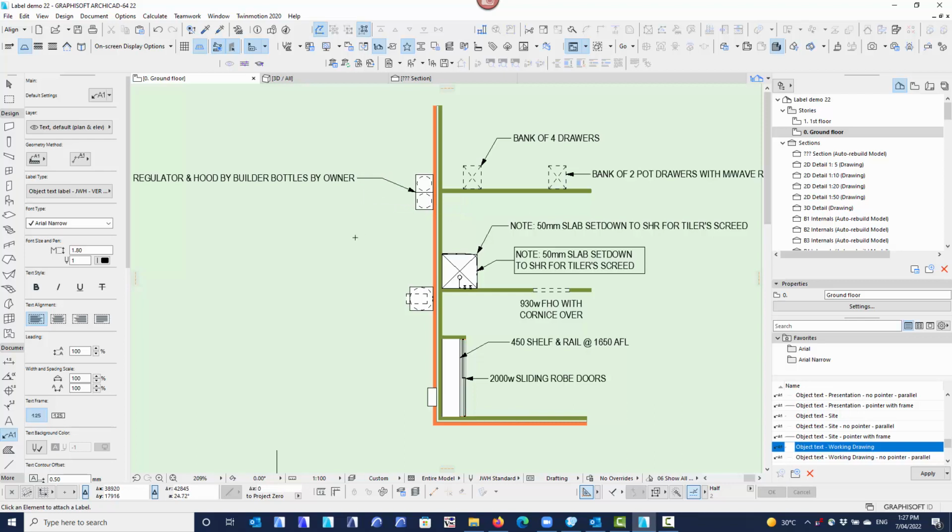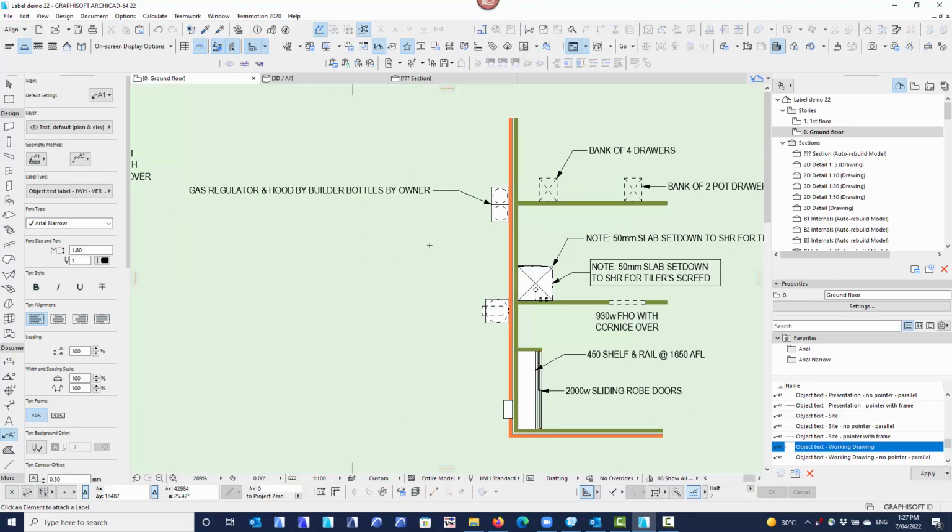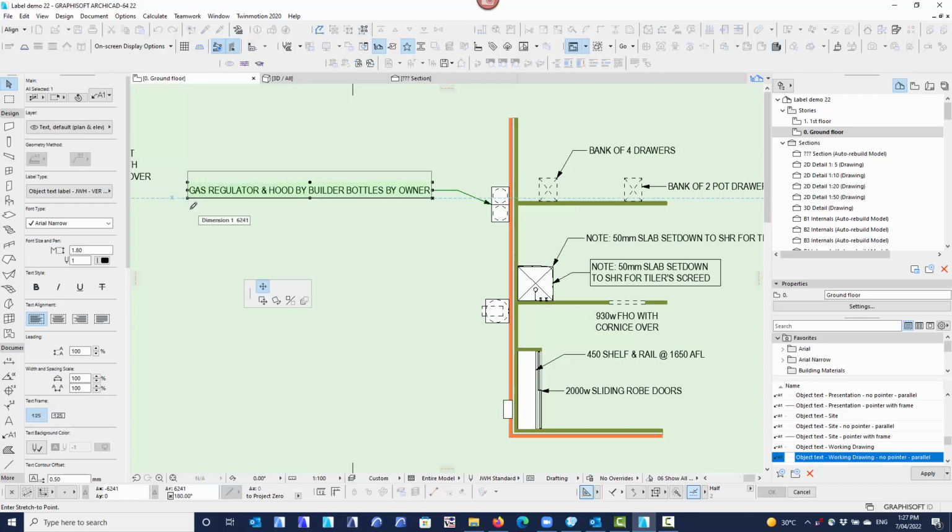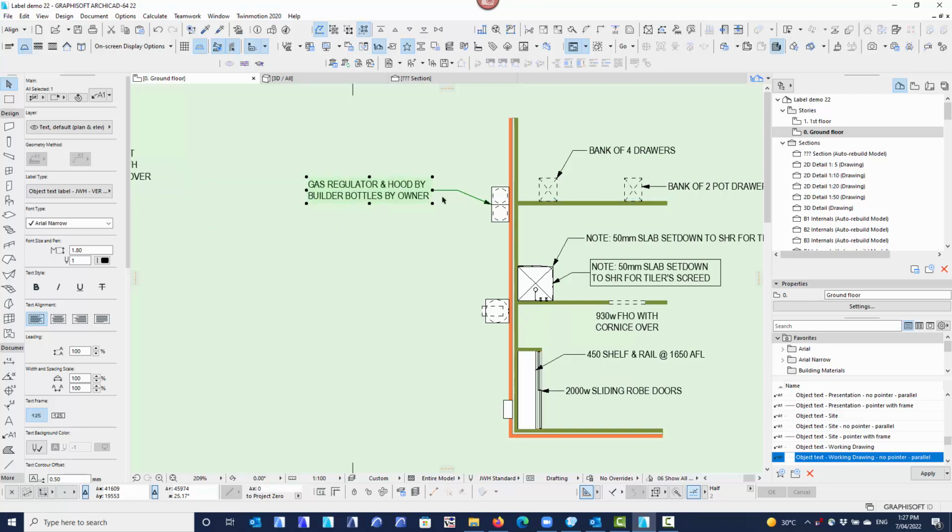It doesn't matter which way, whether I go right or left, it will just go in the direction that you say. All I need to do now is select that and grab the text and shrink it in. Because I've gone to the left hand side here, although I'm shrinking the text this way, you see it actually sliding in the opposite direction. That's just the quirk of the labels, because the text will always adjust from the right hand side. But if I adjust that to say, okay, I'm happy with the 2 lines there, I'll adjust to 2 lines of text. As soon as I click OK, you can see the text moves back to where it should be attached to the leader line.